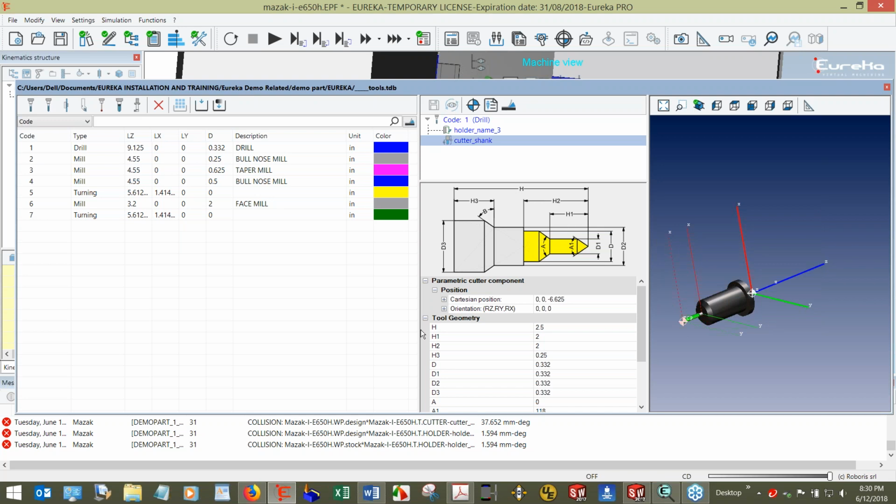Since this is a reverse post processor, you want to go out and prove these things too. But the fact of the matter is that when you get two green lights, one from SolidCAM and one from Eureka, I'd go out to the machine, check my offsets, and press cycle start. I don't have any compunction doing that after working with it. I really don't.